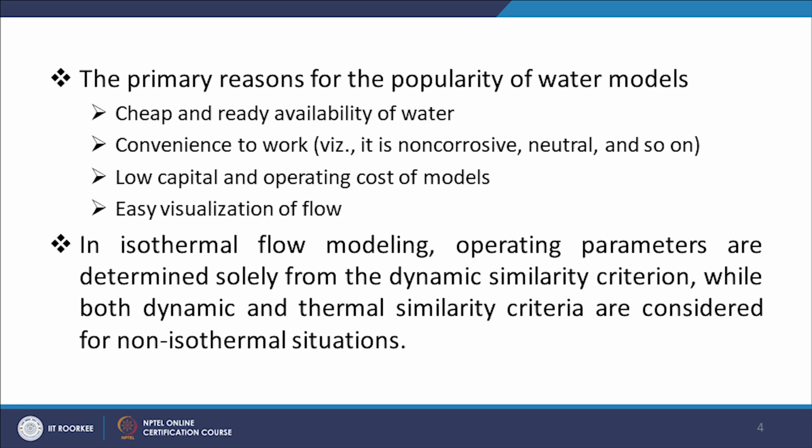So in isothermal flow modeling, the operating parameters are determined solely from the dynamic similarity criterion, while both dynamic and thermal similarity criteria are considered for non-isothermal situations. We have already discussed that for an isothermal system, the dynamic similarity criterion alone is taken into account, but for non-isothermal situations you must also have thermal similarity.